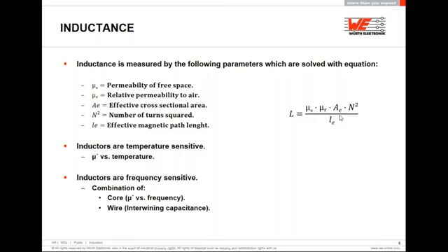We have to be very careful when we calculate this inductance due to the fact that inductors are temperature and frequency sensitive. This means that the inductance value is valid only at a given frequency and temperature. If one of these factors is changed, the inductance changes as well. Always keep this in mind.